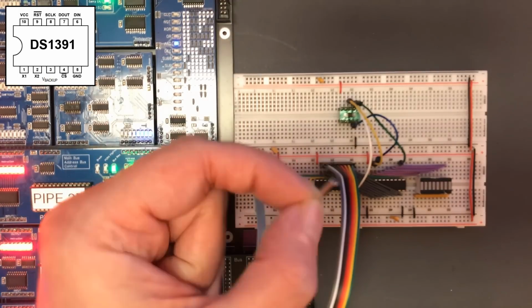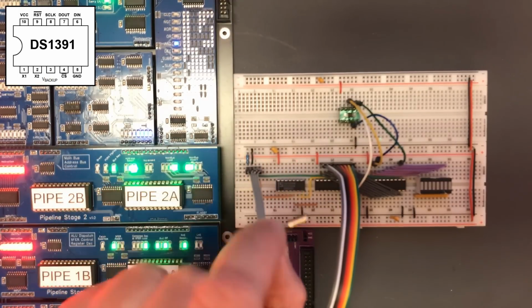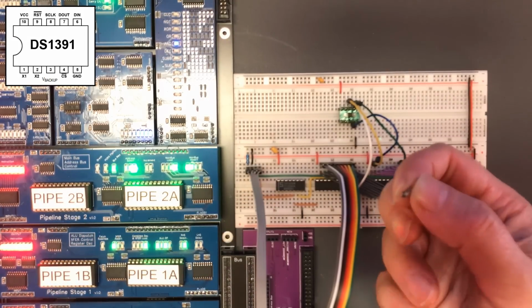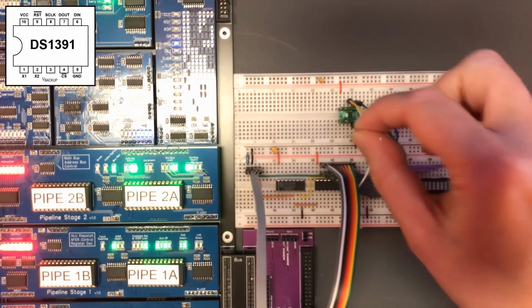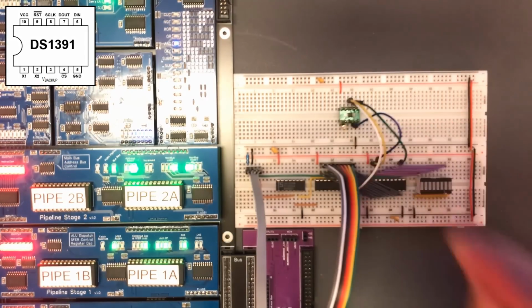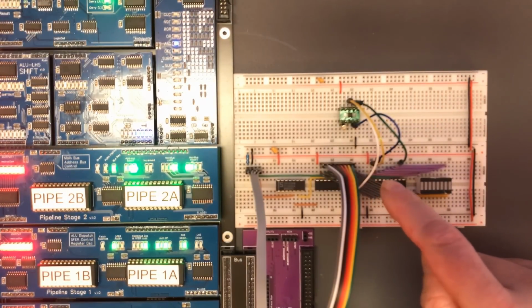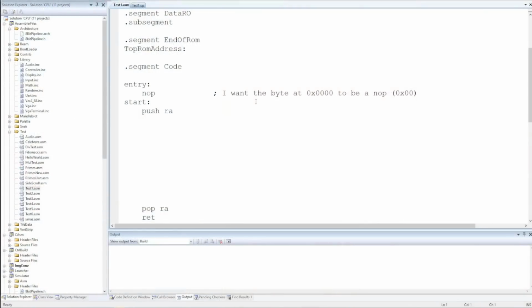Now the needed crystal is 32.768 kilohertz. And when I went and bought one of those, it came in this tiny little package, which I assume is actually designed for watches. I think we can get away without connecting the backup lines at the moment. In theory, we've got what we need. We just need to write some code if we're going to bit bang these lines. And I think it would be best to start off making some definitions to make our code a bit easier.